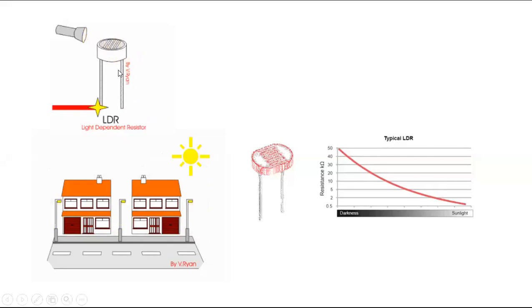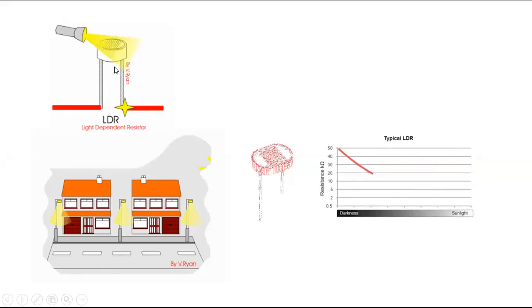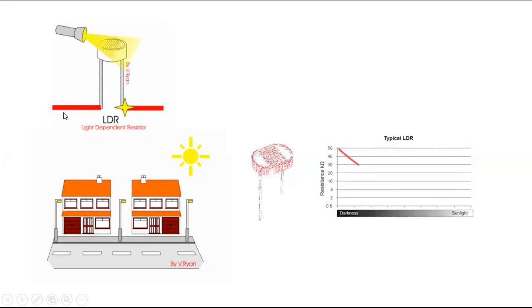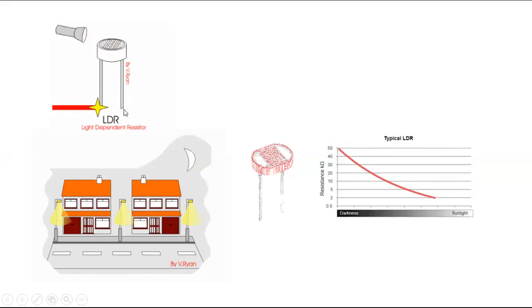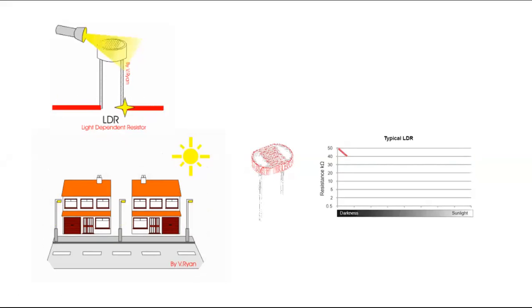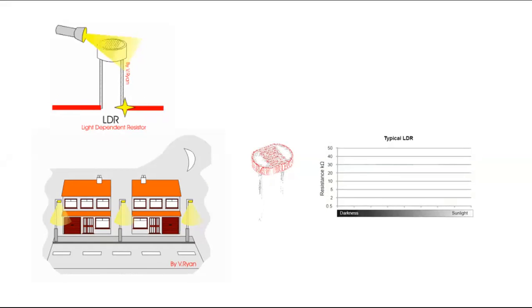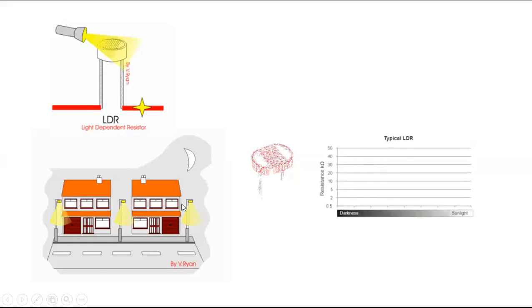So as we have discussed, whenever light of suitable energy falls on the photoresistor, the resistance of the photoresistor decreases. As a result, free electrons will move from one place to another, and hence the current flow increases. So this photoresistor is used in solar lamps everywhere, and it is especially used in automatic street lights. Nowadays, if you see the street lights, after 6 p.m. automatically they are on. During night time, the photoresistor makes the street lights turn on, and during early morning, automatically the street lights will be off.